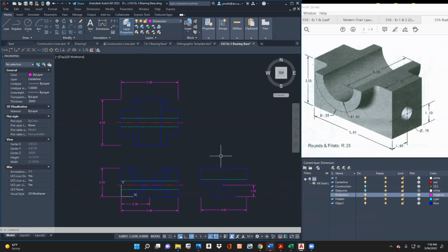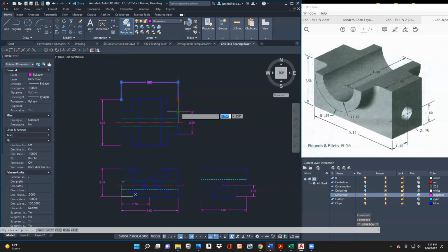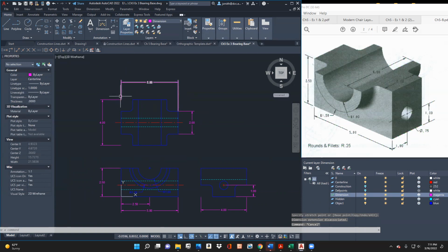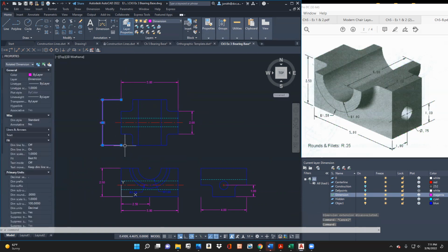And so I could then go through here and just try to follow the dimensions that I'm seeing in the book. I'll just do that rather quickly. And then I'll call this a day. So it says 2 inches there. I'm just going to put some basic dimensions on here. I'm not going to go crazy, but I want to show all the dimensions that it shows. I notice I need to change some of these. Yeah, so a couple more here, 5 inches. So what I might do at this point is be a little bit more consistent here, snapping to my object where I need to.